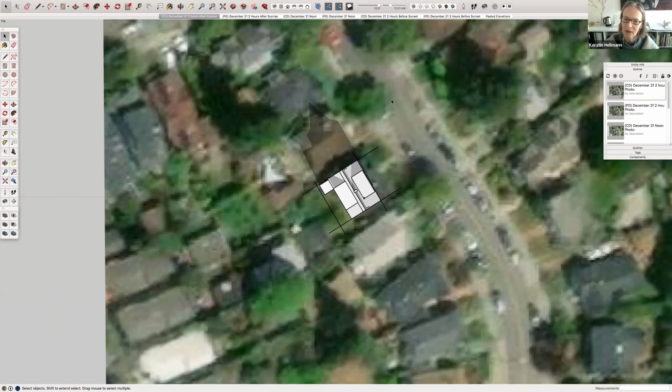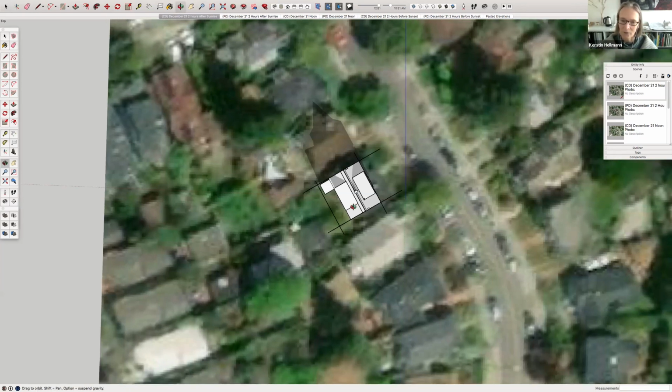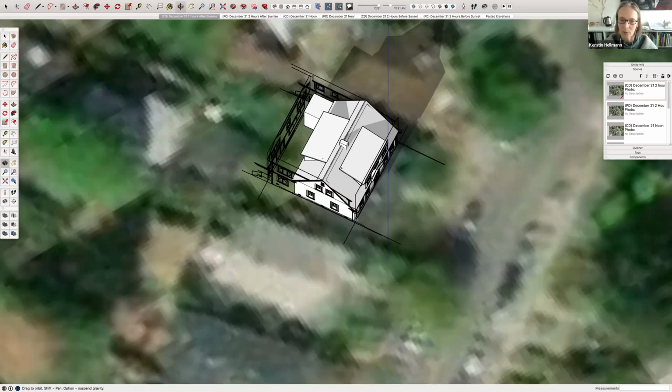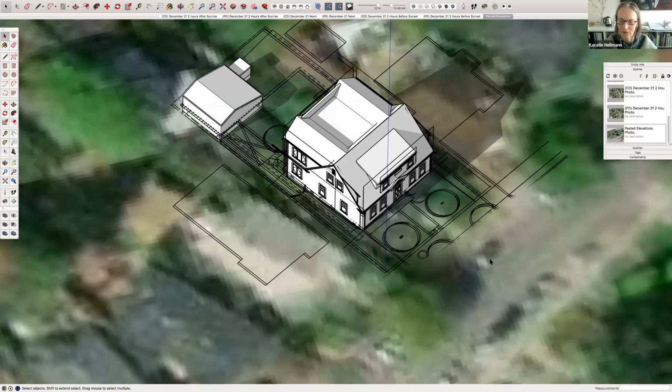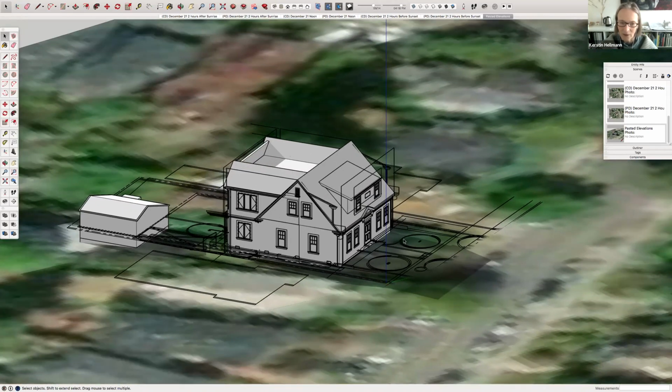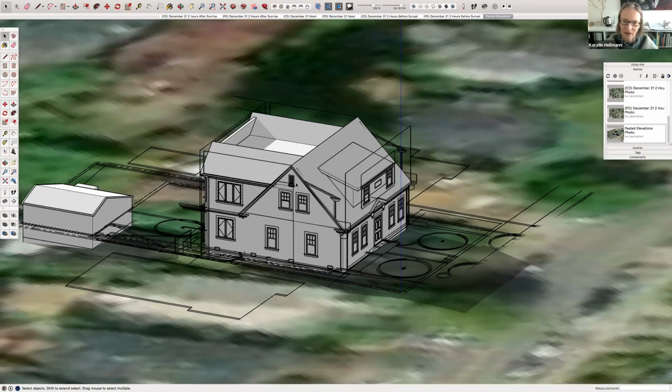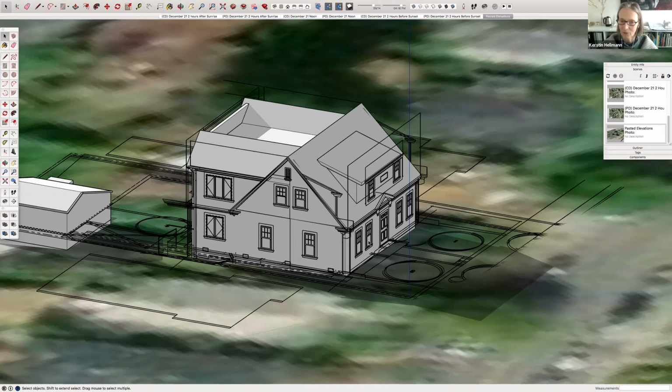So you geolocate this plan, which means you grab a Google snapshot of the area where your house is located and just bring that into SketchUp. I'm not going to show you how to do it right now because I'm too nervous, but it's very simple. Then you go into wherever you created your files of the house and import the DWG files of that. That's what this scene called pasted elevation shows. It shows you the site plan, and then you just set your elevations, rotate them the way Andy just showed how you rotated the window. You can rotate your elevations, you pop them together, and they'll create a solid face where the elevation is.